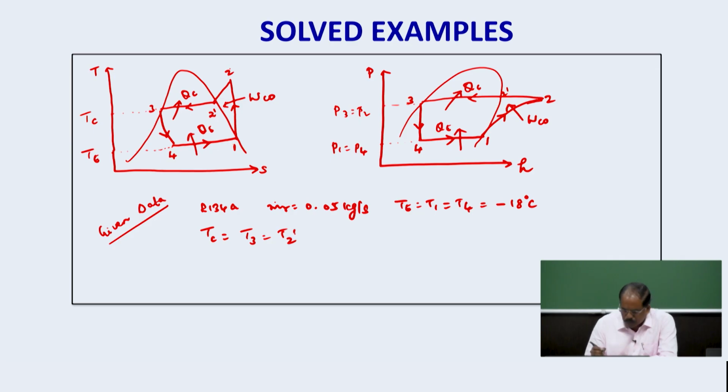Because when the condition of the refrigerant at the inlet of the compressor is dry and saturated, point 1 is already lying on the saturated vapor curve. So when the refrigerant is compressed, the state point after the compression process is completed will be in the superheated condition.